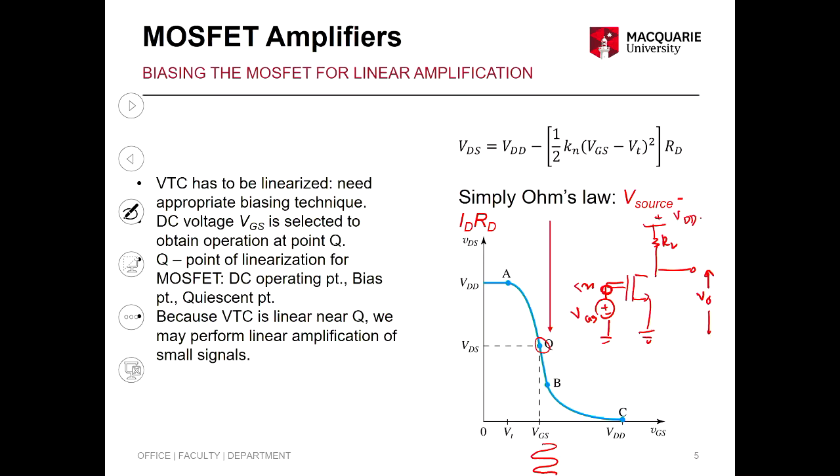Now, based on your amplification, let's say your signal variation is sinusoidal, you will also have a corresponding variation at the output. If it goes this way, the level out through here will go the other way. So the gain of this circuit would be, my signal changes here, say amplitude A1, and then here A2. My voltage gain, AV, would be A2 divided by A1.